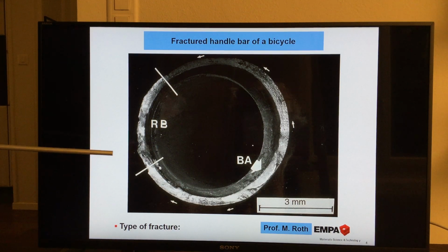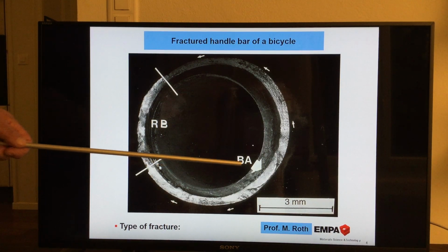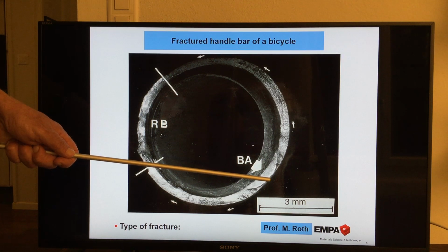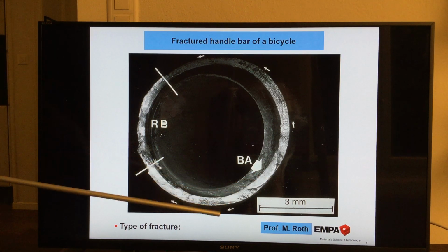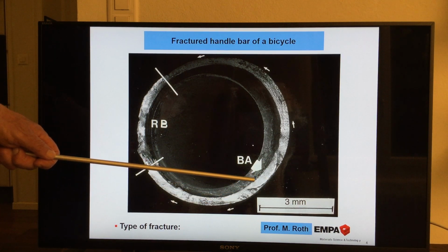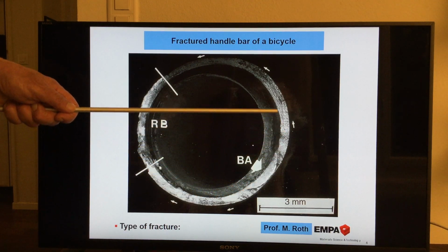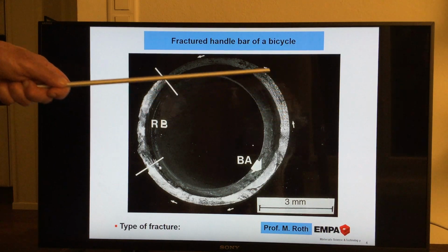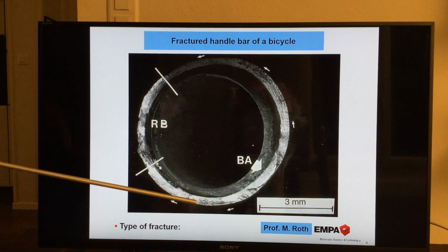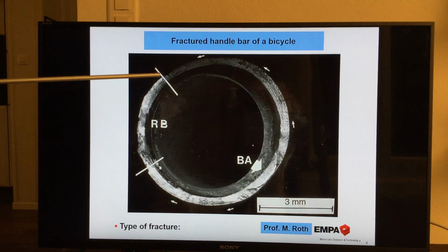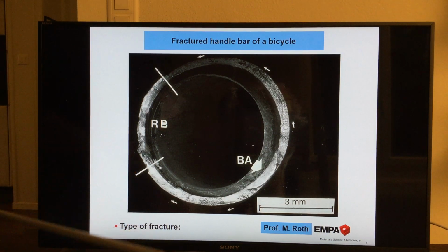When we also watch now what's happening with this crack, which is first propagating here, then approaching the outer surface, the crack obviously turned direction in both sides and propagated, shown here by the arrows, in both directions. And now you imagine what is the last part here. This you also already know. This is our overload fracture.